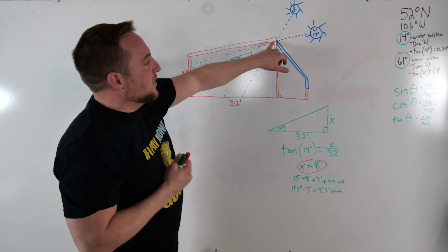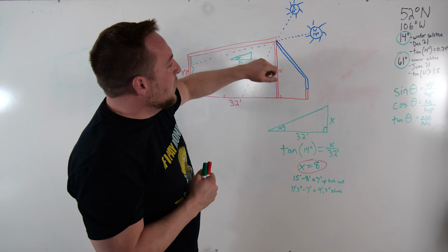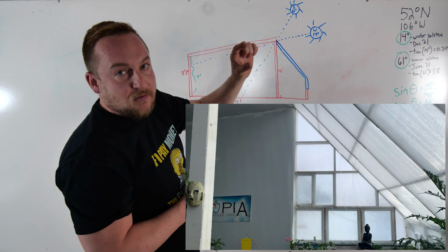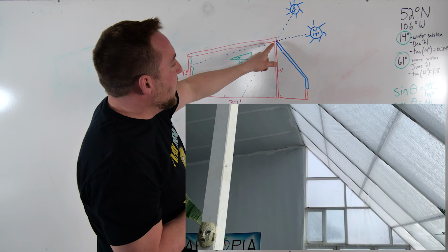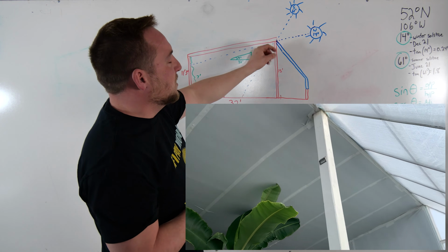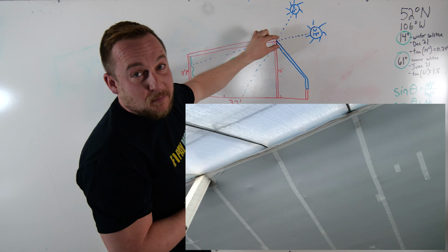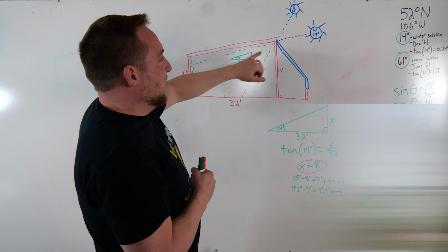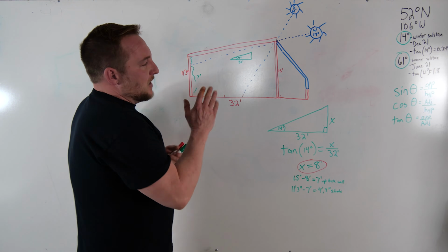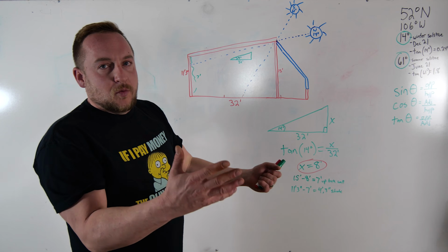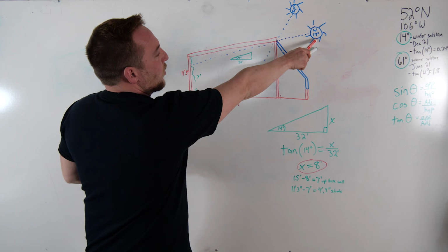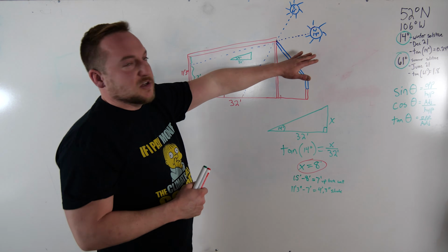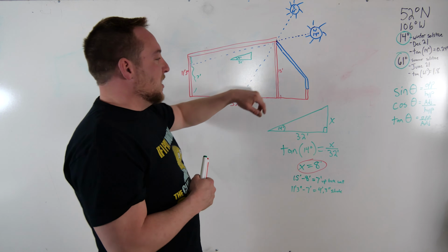The shading function of the greenhouse starts at the beam. Now, I didn't put a beam and the trusses on top, because then I would have a beam that would shade. So I hung my roof system off of a beam with big hangers, so I didn't have any shading from a beam, right? But anyways, what do we know? We know the angles, so 14 degrees or 61 degrees in the solstices. So let's talk about the deep winter aspect of it, 14 degrees.